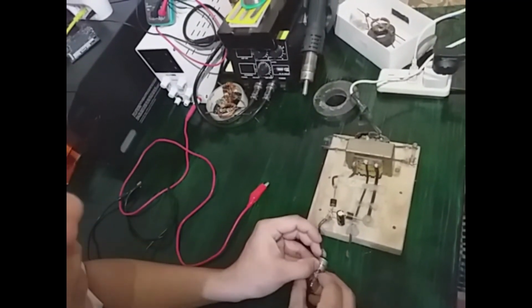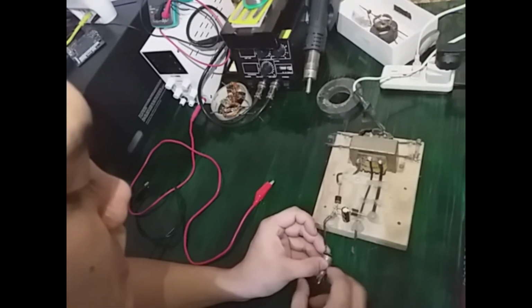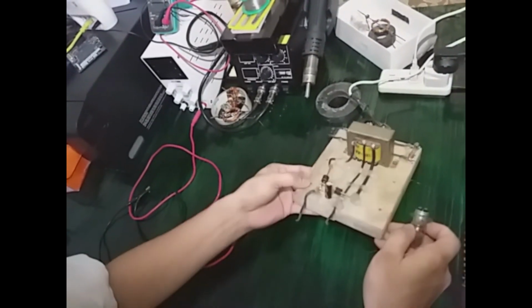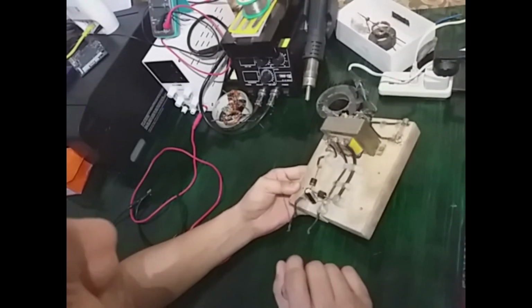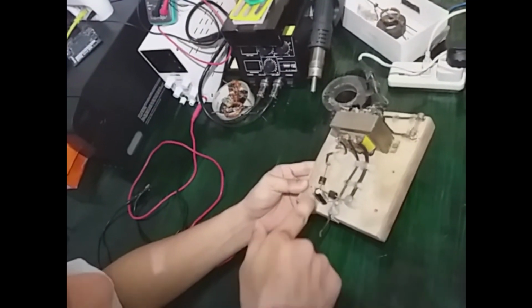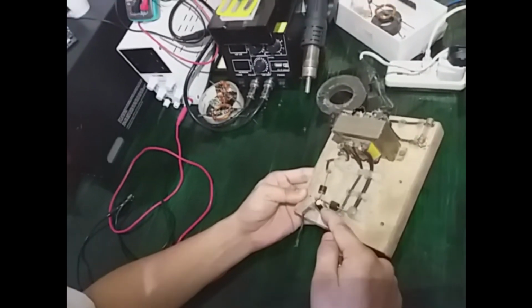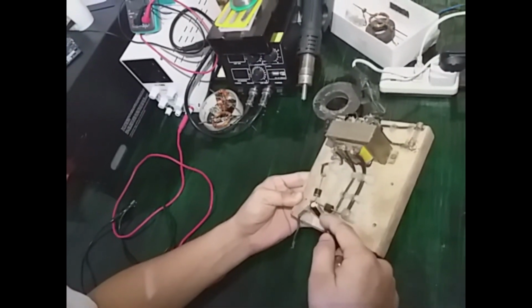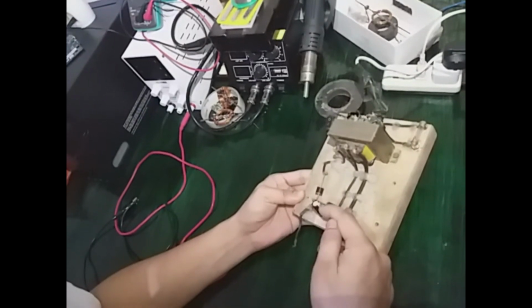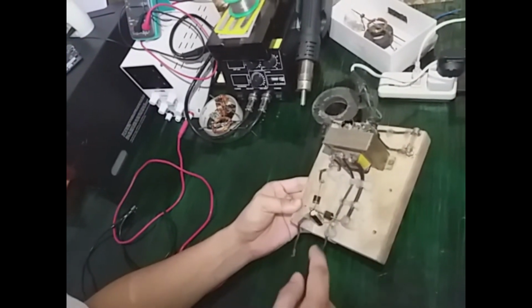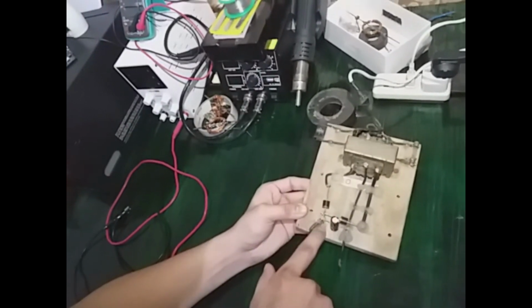Then we connect the positive and negative terminal. Now, for you to be able to know which is the negative terminal and the positive terminal of this one, see the filter capacitor. We have here an indication. So we have here a negative, so this implies that this terminal is negative since we have this indicator, and the other side is positive.